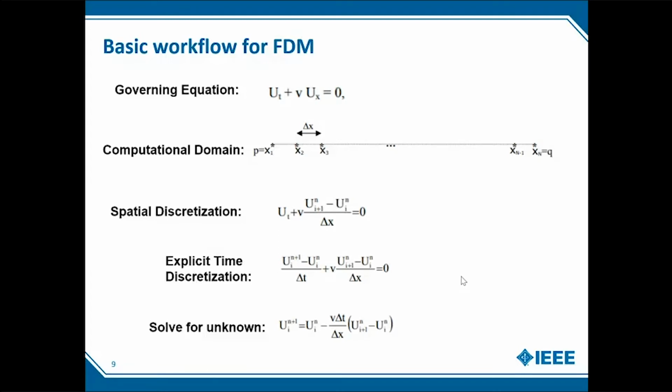So you see, if you have used any CFD solver, you'll see a residual plot coming up. You'll see residuals of 10 to the power minus 3, 10 to the power minus 5. What those residuals mean is basically just the error between the current time step and the next time step. So that is what you are seeing on that plot. In order to achieve an accurate solution, you need to have error less than 10 to the power minus 3 at least. And the lesser the error, the more accurate the solution.